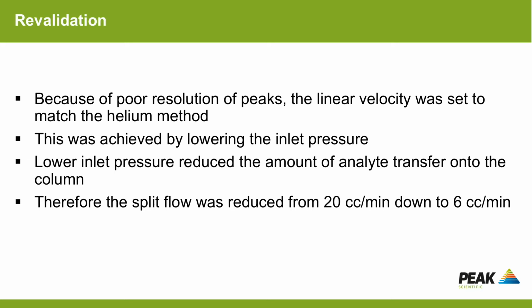And this lower inlet pressure actually reduced the analyte transfer onto the column. So because the customer was using split injection, they were able to reduce the split flow to increase the concentration of sample being injected.